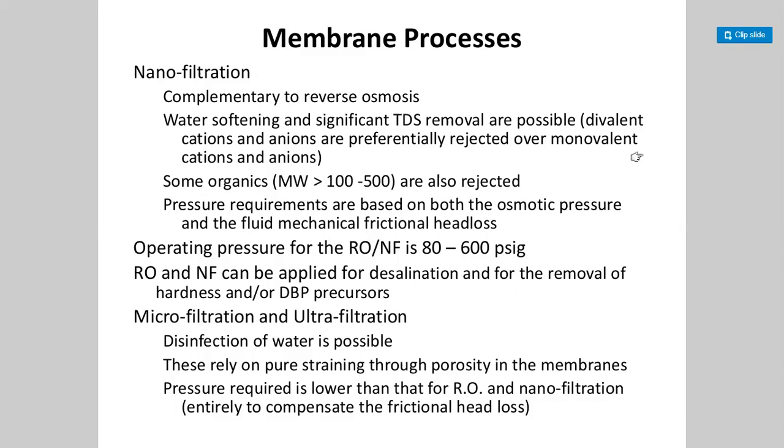In microfiltration and ultrafiltration, disinfection of water is possible. These rely on pure straining through porosity in the membranes. The pressure required is lower than that for RO and nanofiltration, only to compensate the frictional head loss.